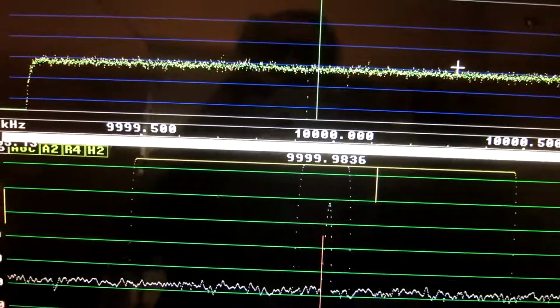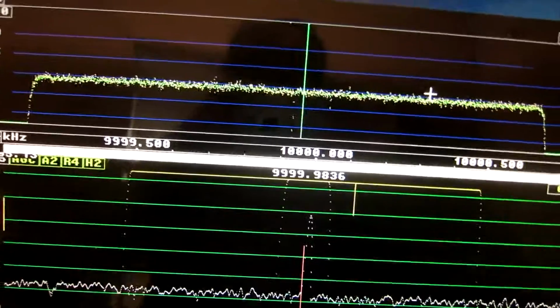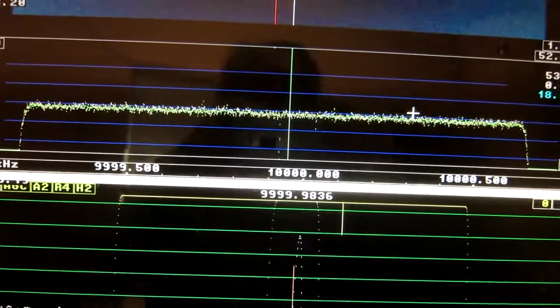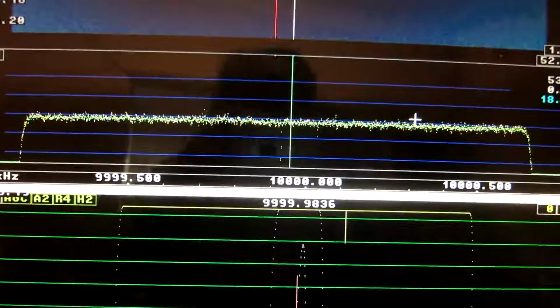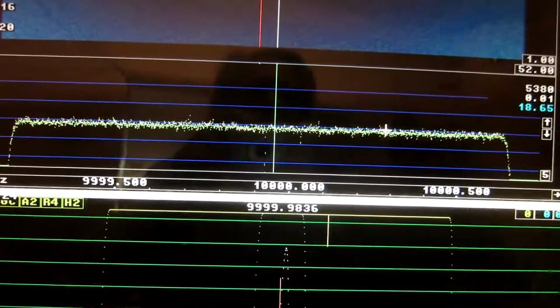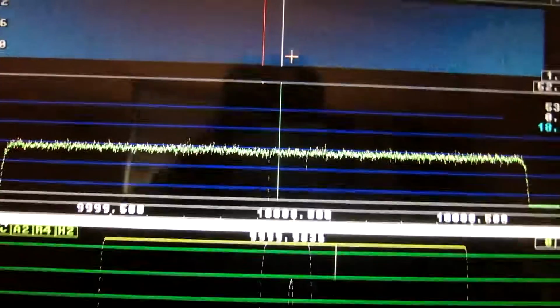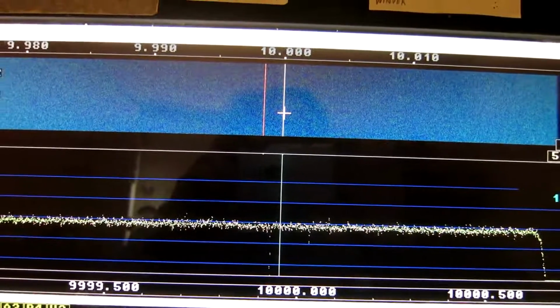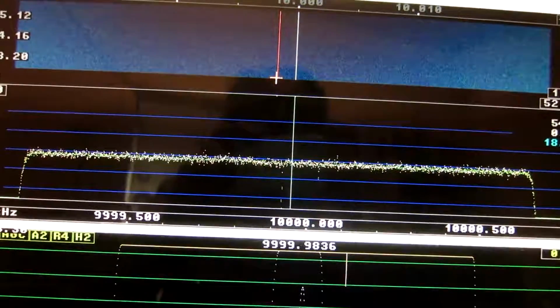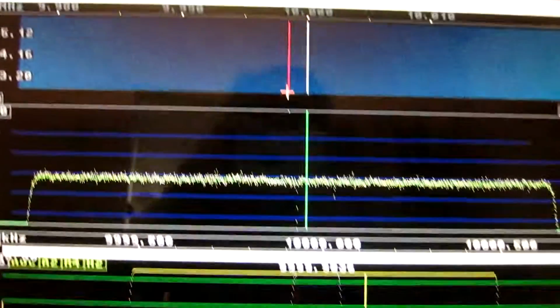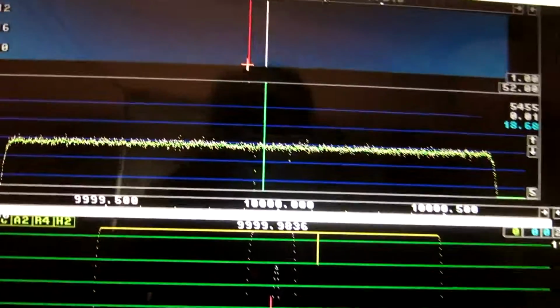First I run as a normal receiver, as a spectrum analyzer. I have calibrated Linrad carefully, so I have the signal here at 10 MHz. DC is here about 700 or 750 Hz below.